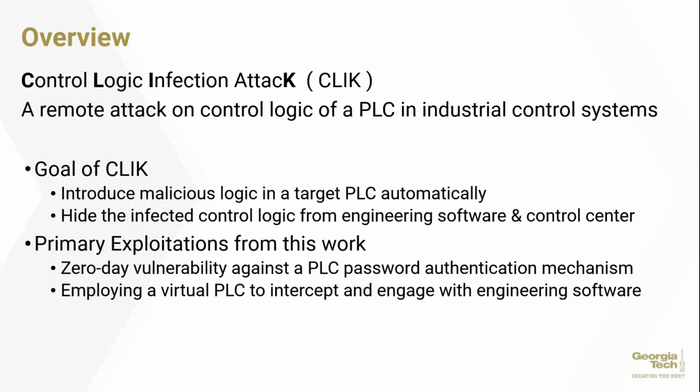Now, CLIK stands for Control Logic Infection Attack. It's a remote attack on control logic of a PLC and industrial control system. The goal of CLIK is to introduce malicious logic in a target PLC automatically and hide the infected control logic from engineering software or control center.